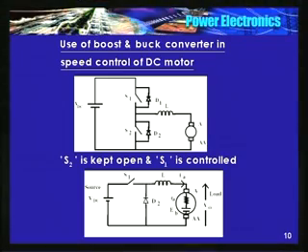Okay. Now coming to the application, see what I am doing. This is a circuit, a DC source. I am taking two switches, S1 and D1. In fact, I do not need to connect a separate diode across a switch. Any controllable switch you take, either a BJT or an IGBT or a MOS, there is a built-in diode. Okay, this is a freewheeling diode connected across S, which is built in. I will take two switches, S1, S2, an inductor and a DC motor, the armature here.